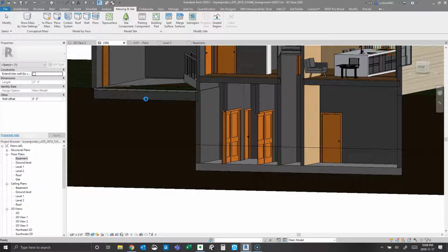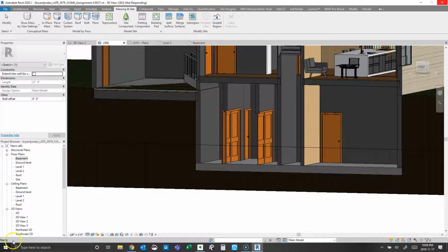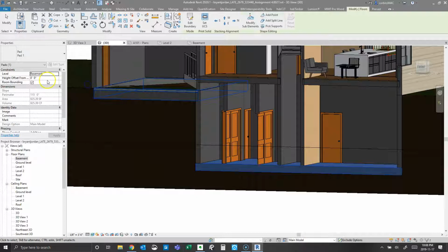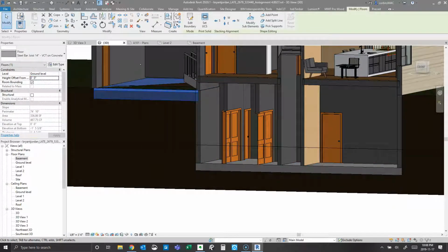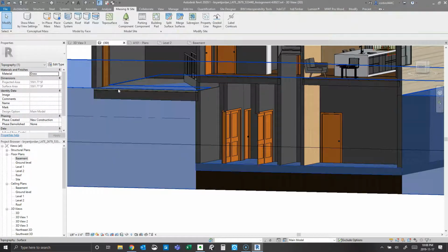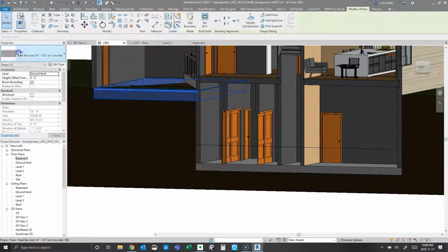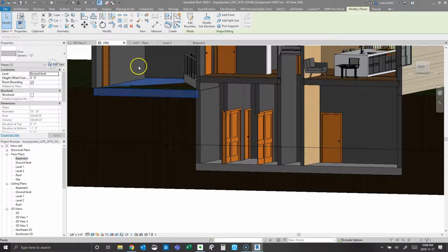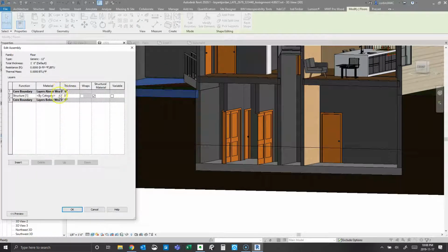So is this a building pad here or is this a floor? I'm not sure why my computer's being slow. Yeah, so this pad right here in the garage, I'm just gonna bring. No, it's a steel floor. So this is not completely necessary for the garage. The garage, you just want to have a floor 4-inch. So I'm just gonna go to generic. Just make this a 4-inch concrete slab.